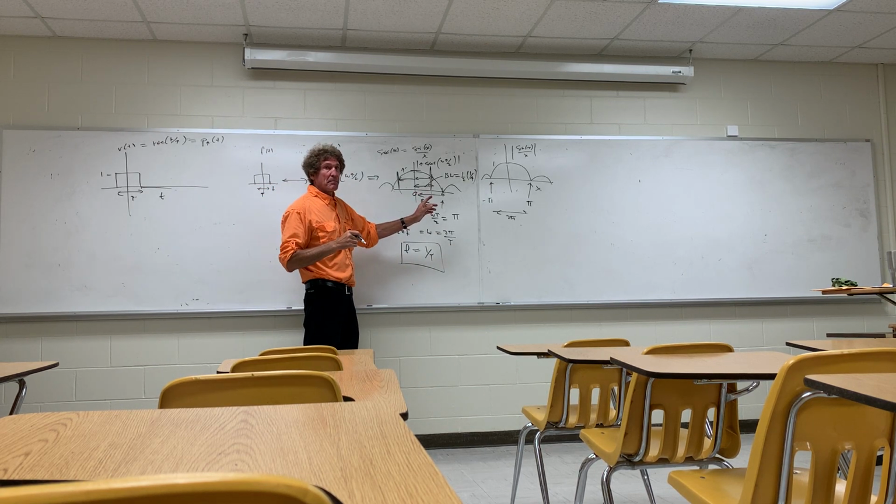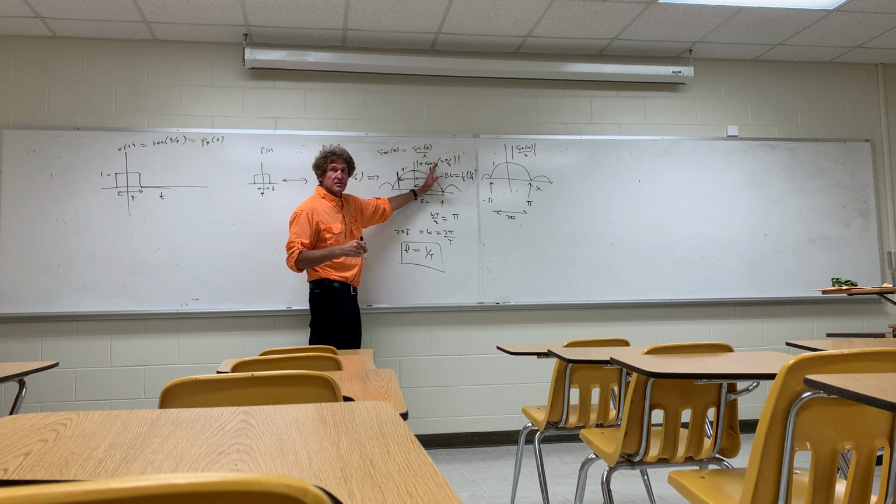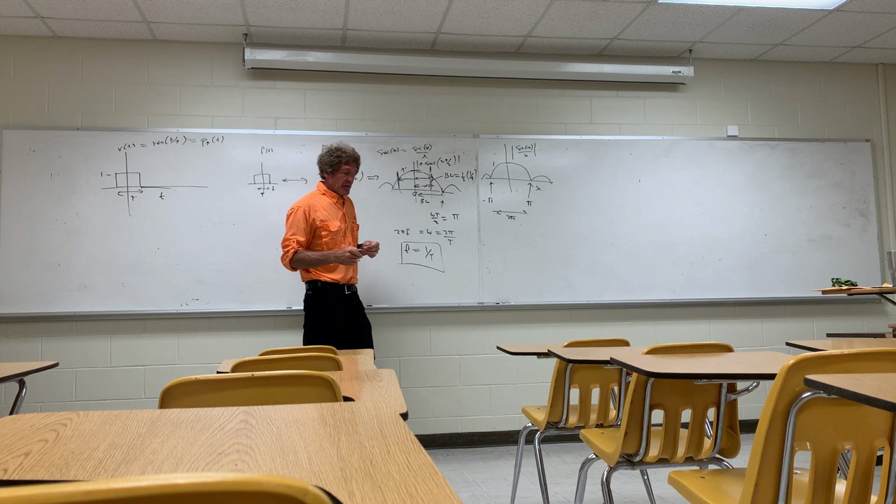Usually when they talk about bandwidth, it's 1 over tau. For radar work, it goes to the absolute null. But in his book, he's talking about the half power point. So that's the only difference. Do you follow me? If you think that goes to tau, half of that is about the 0.707 value of the sine function, roughly. Not exactly. That's how come he has it.